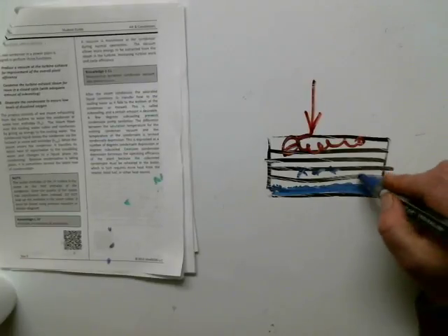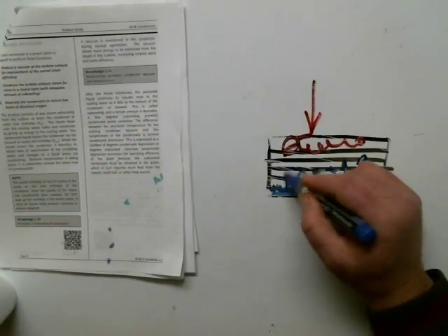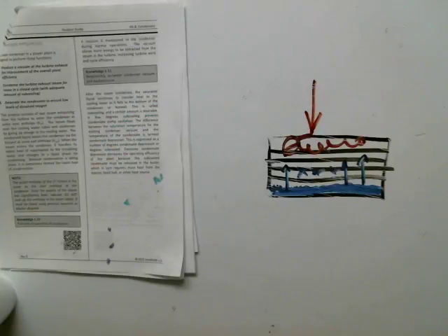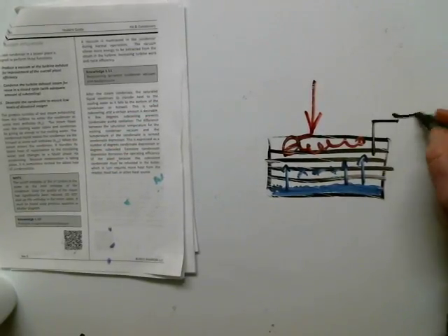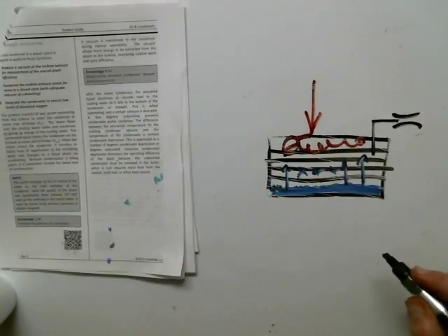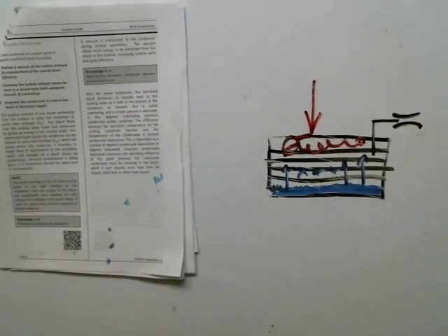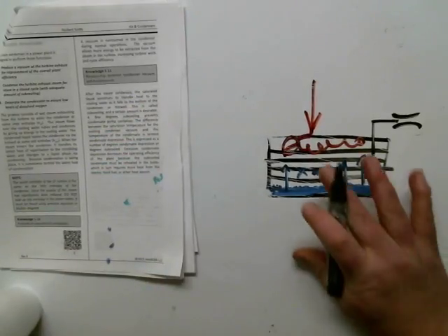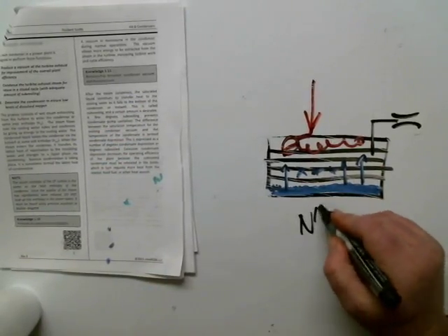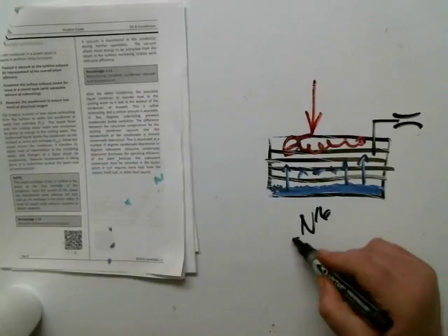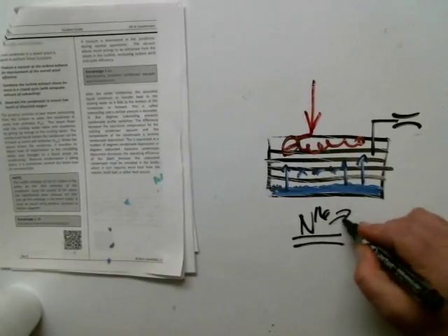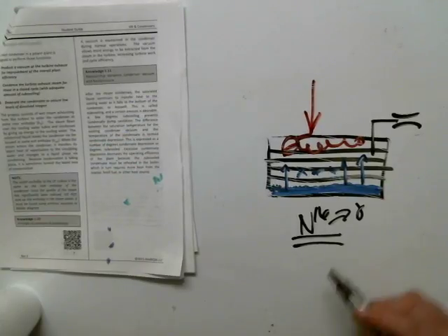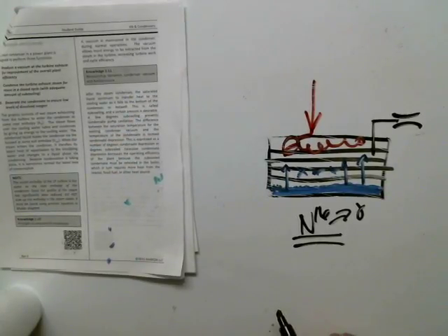Also, the condenser, once it enters here, it's going to allow deaeration, to deaerate the condensate. And I know that steam jet air ejectors can take a suction on this, and I can remove the air and non-condensable gases. Another thing is it allows a certain amount of stay time for nitrogen-16 decay gammas. So I'm not transporting these gamma emitters around the plant. I'll allow them time to decay away. So condenser application has a lot.